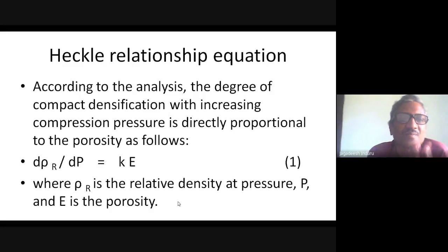The material falling between the upper punch and lower punch gets densified, which means its volume is reduced and its density is increased with increasing compression pressure. In the previous sum, you could increase the compression pressure by decreasing the distance between the two rollers.